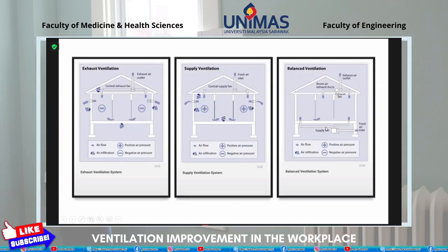And thirdly, we can introduce balanced ventilation. With balanced ventilation, we can do both: supply the fresh air with mechanical ventilation, and also exhaust the air with mechanical ventilation. Most of the time, balanced ventilation will create almost neutral pressure within the room.